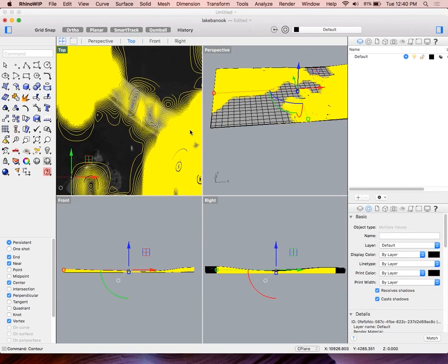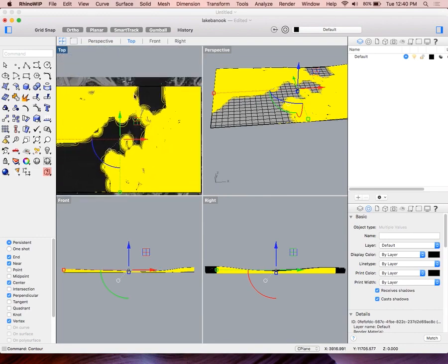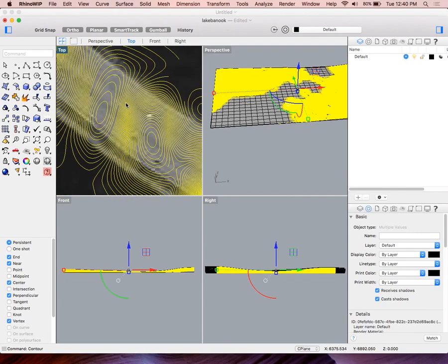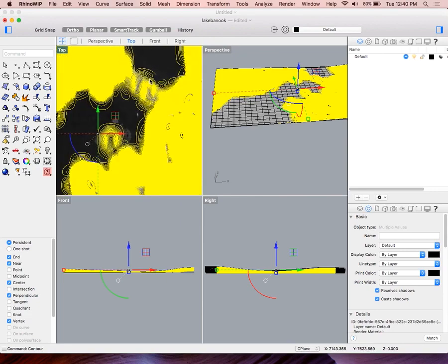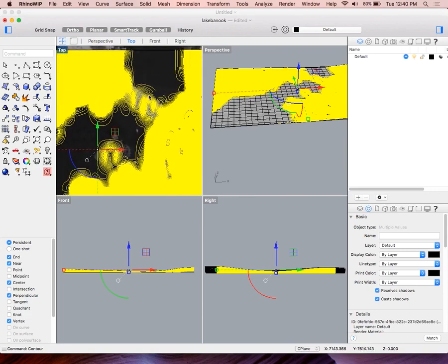It's getting the gist of it, but things in, say, this area, this was a problem that Jeff and I were having yesterday, because he was trying to build his contours with his road on it, which you really shouldn't do. It then thinks that there's a buildup all the way across this little lake, but actually you can go underneath it, right? So it's open for boats to go underneath this road. So things like that you have to be careful with.